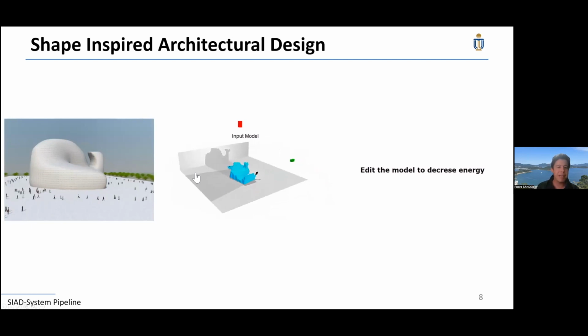So basically, to accomplish this, we try to generate a voxel model according to the silhouettes, to preserve the silhouettes so that when viewed from different angles, you get the correct look, right? So in the particular case of this optimization, although this can be generalized, we employ 2 cameras on the ground, since usually you view the building from the ground, right? And 1 camera from the top, which is essentially the footprint of the building.